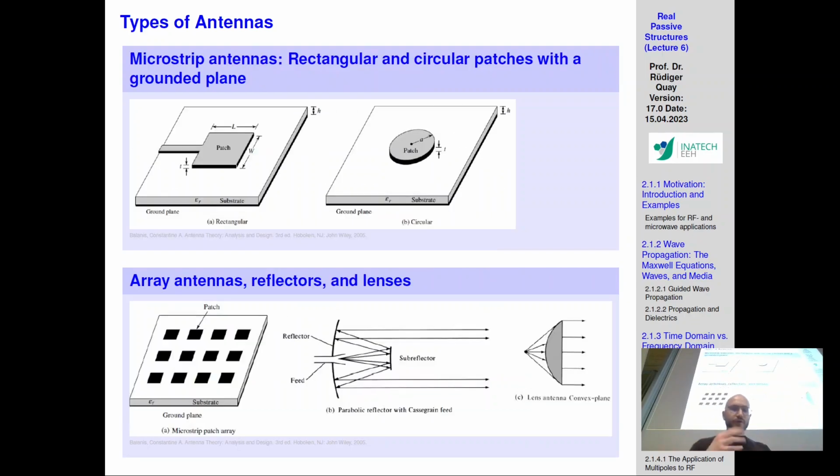We then discussed more modernized concepts. These have been concepts that have existed for the past 30 to 40 odd years: patch antennas, which use a dielectric substrate to generate a certain mode, to generate fringing fields and surface currents, and by introducing an interrupt or an edge length of lambda half, you will be able to have a certain mode of radiation at a certain frequency point.